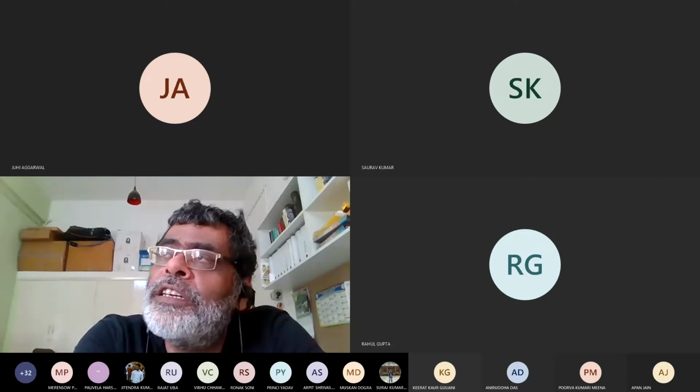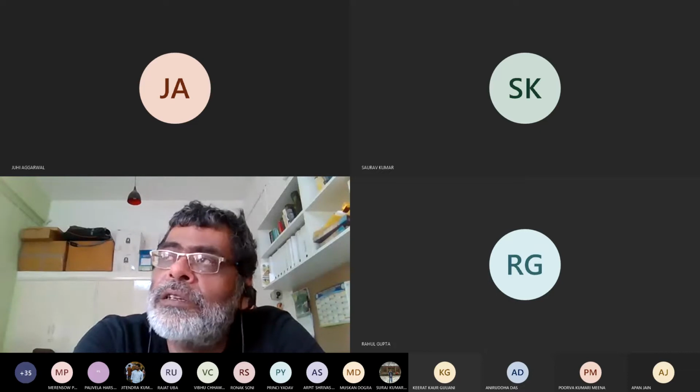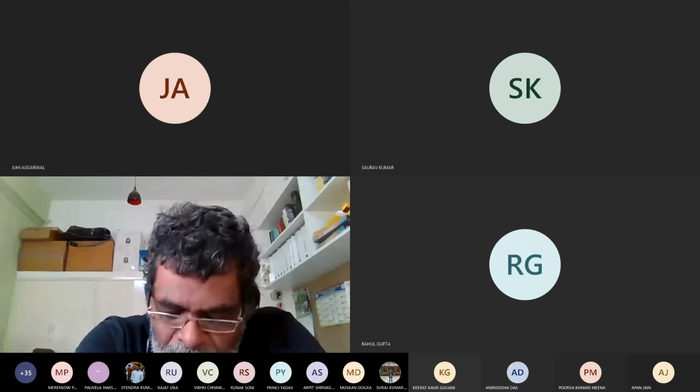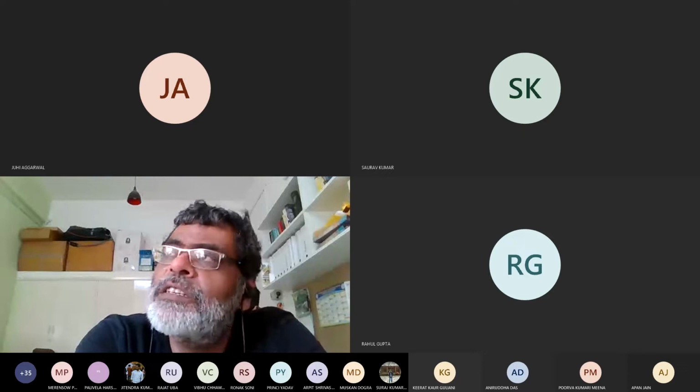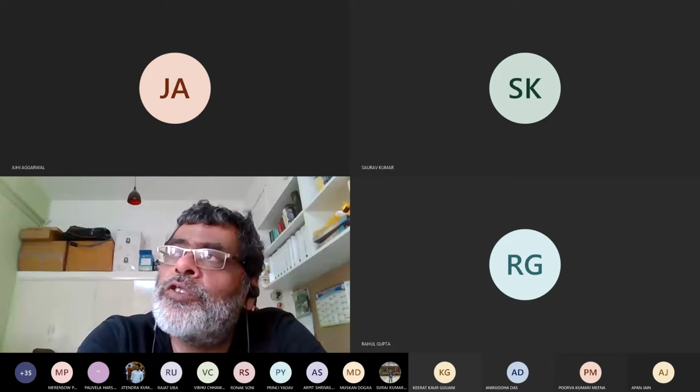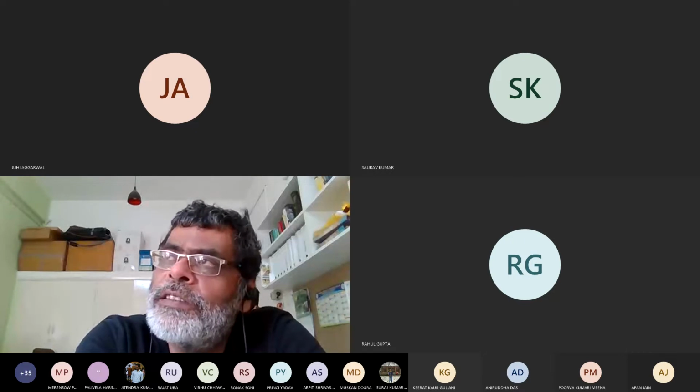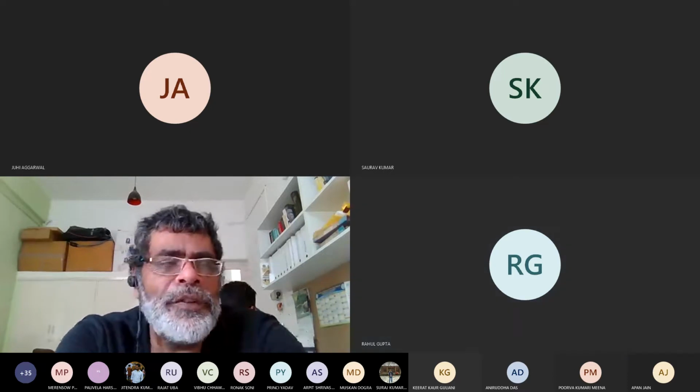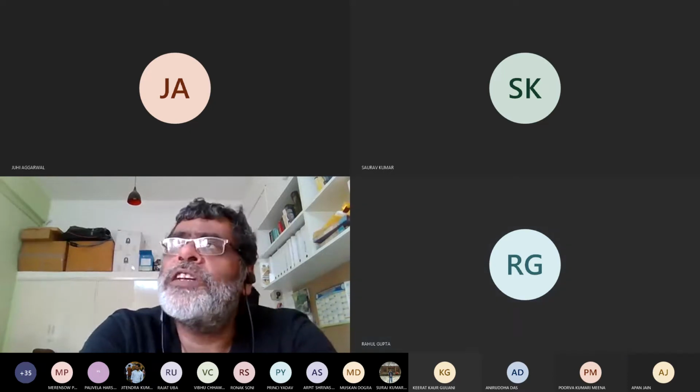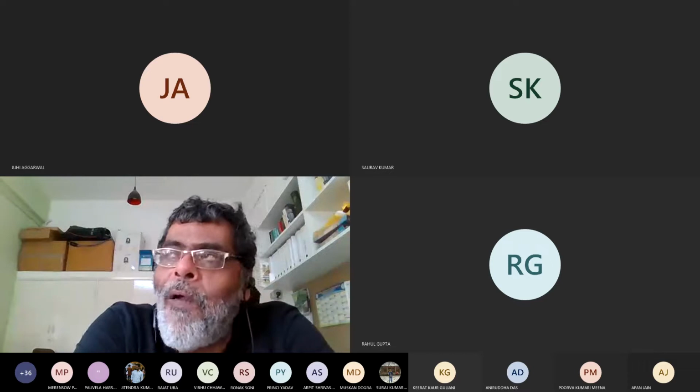And you end up getting a series of equations, K times X, where K is your stiffness matrix and X is your individual displacements, is equal to F, which is your external virtual work system. Are we good with this? Yes, sir. So the statement we are making is that your internal work is equal to your external virtual work.